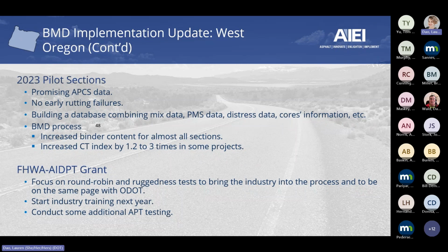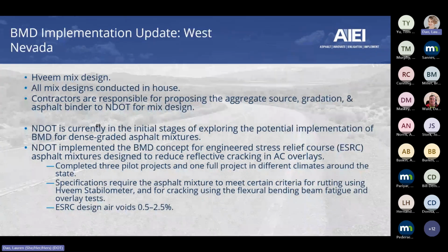what we've observed with other states or other contractors was really a change in their gradations, certain types of stockpiles, the binder source. So they have to tackle other things, right? There's a lot more to balanced mix design than just, we'll add another 0.5% or 1% of asphalt binder, right? I just want to make sure. That's why that tech brief is important. If you want to go through it, you'll see what those different changes are.